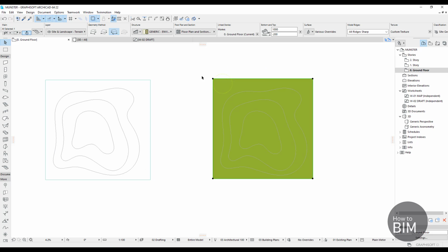If you select the mesh and select the mesh tool and then use the magic wand, so again hold the spacebar, as you can see it changes my crosshair to this magic wand, and then find the spline and click on the spline. It will open up a tab where you can create new points in our mesh.